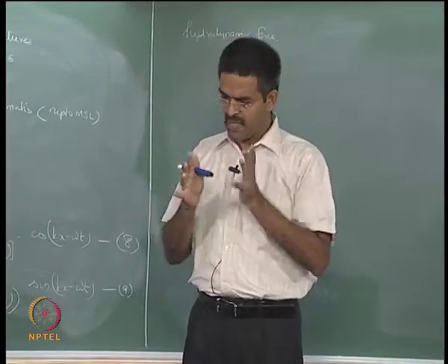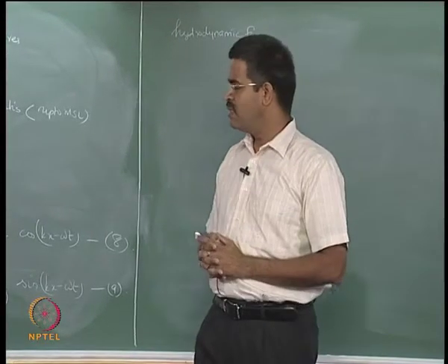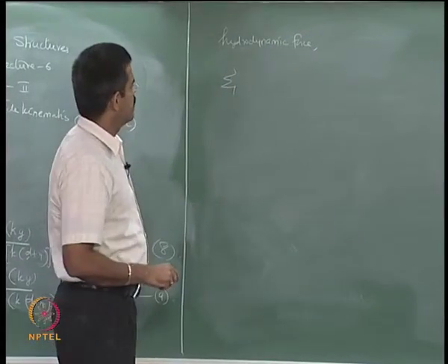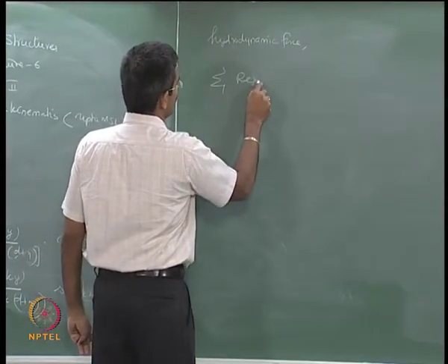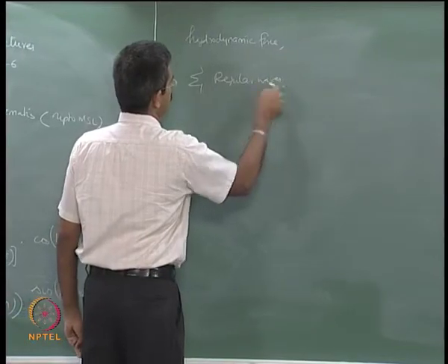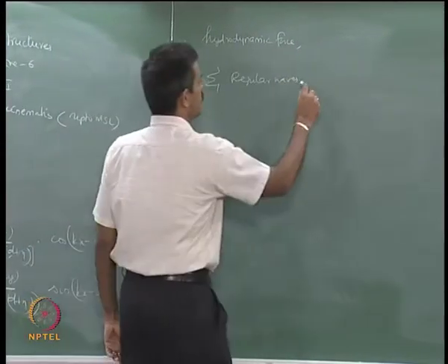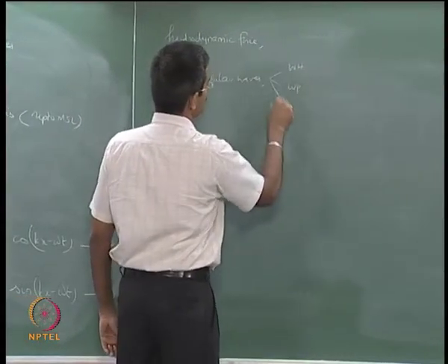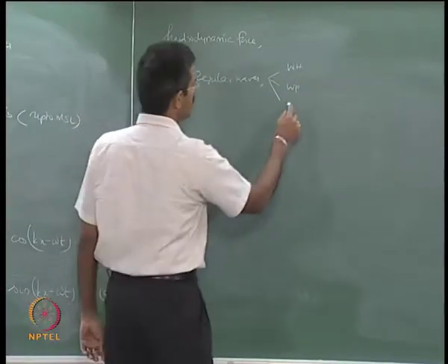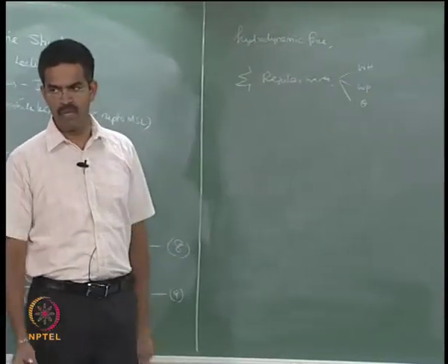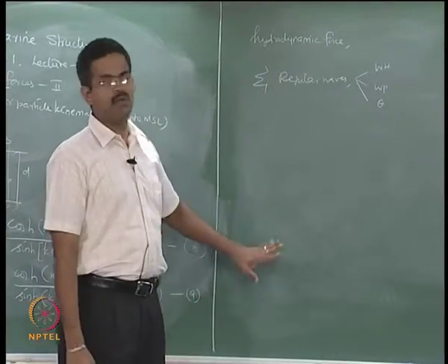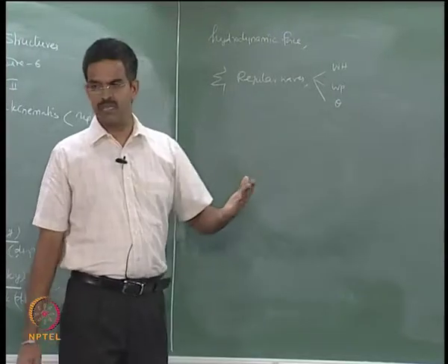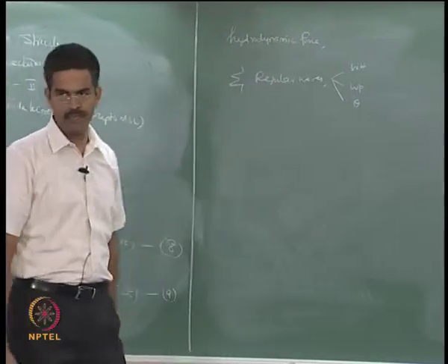This n can be a finite number, or n can be infinite, which will have the summation of components of regular waves. The wave amplitude can be different, the wave period can be different, and of course the wave direction can be different. If you put all of them together, then you will be able to really simulate an original wind driven open sea state to which a marine structure is exposed.